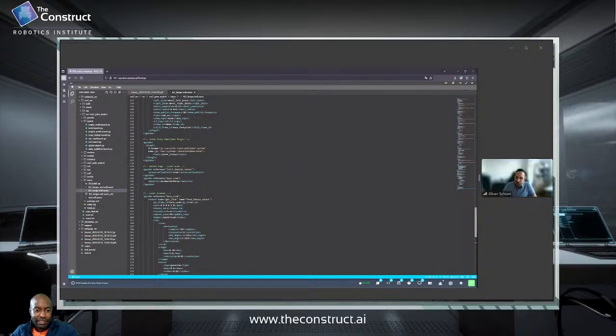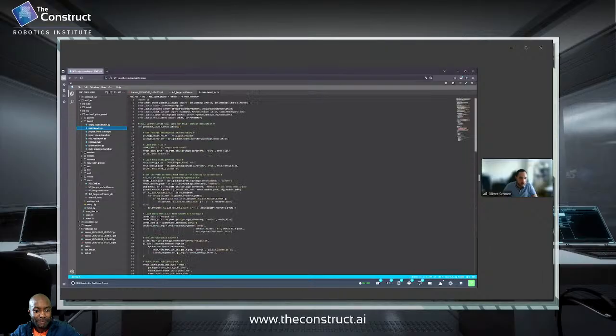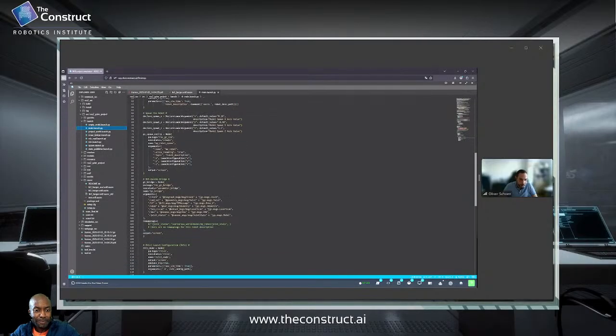Oh, now I'm a bit confused. So when I'm using the real robot, basically the robot is providing the joint states, right? So there is a joint state publisher, I'm not sure running in your system, but it's already providing the joint state topic. For the simulation, I have to do it myself or start it, so that's why I have this joint state publisher plugin here, where it also has the joint states topic. And when looking into my bridge, I also have the joint states here being bridged from the Gazebo part.